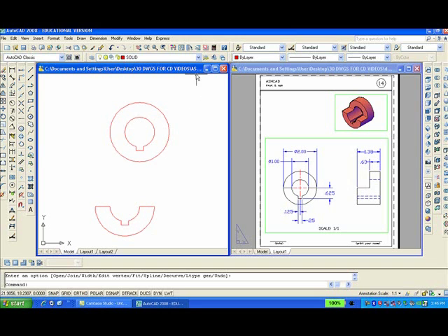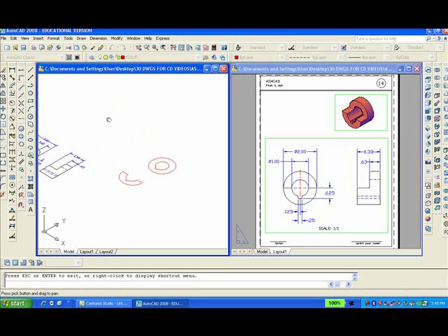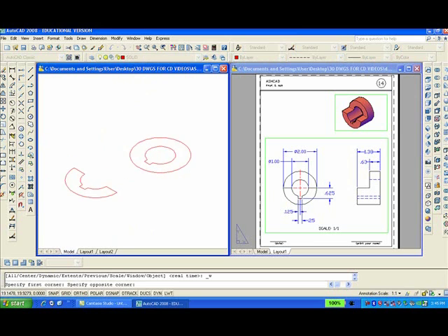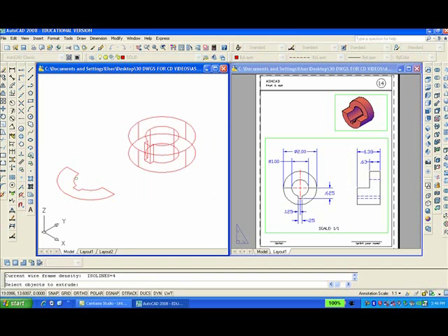And we're free now to move into southeast isometric view, to pan over and zoom with the window to enlarge what's going to be the solid. Now you'll want to type EXT to extrude, and we'll select this portion. That's going to be a height of 0.63, enter. And we're going to extrude this portion, and that's going to be a height of 0.75, enter.